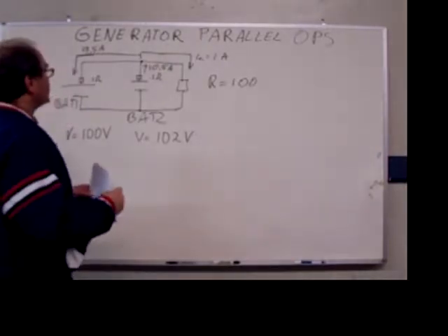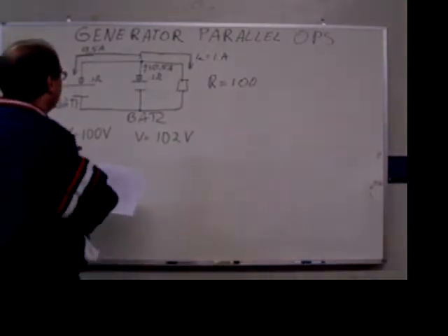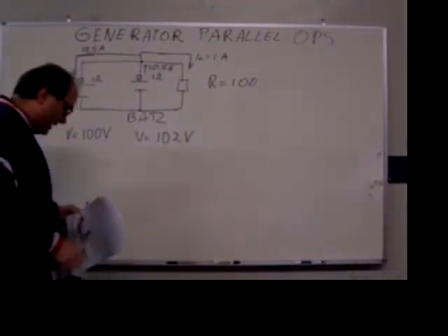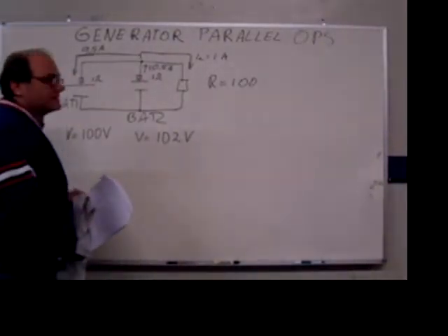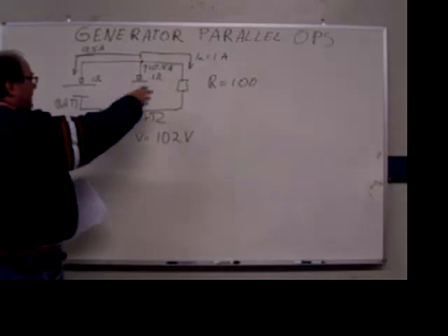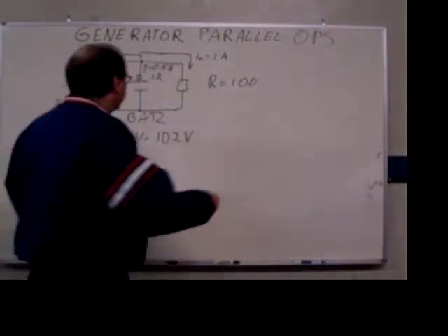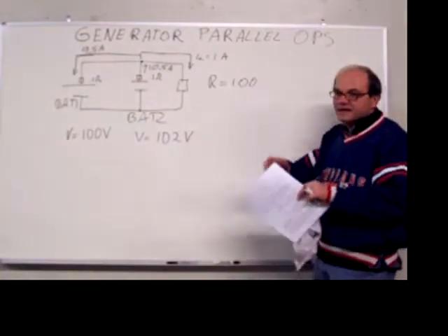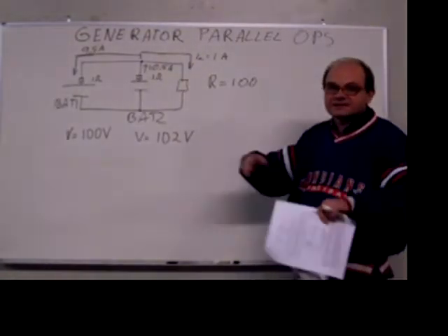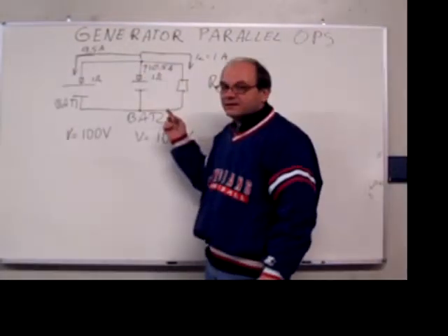So in the beginning, when the system is first hooked up and connected, that's basically what you're going to have. That is important when you work with power supplies or with systems like solar panels and battery chargers for windmills, because you usually parallel a bank of regular lead-acid batteries, and you combine series and parallel connections. When they're first hooked up, before you charge them, you have to let this whole system sit for several hours until there are no more currents going between any of the parallel batteries.